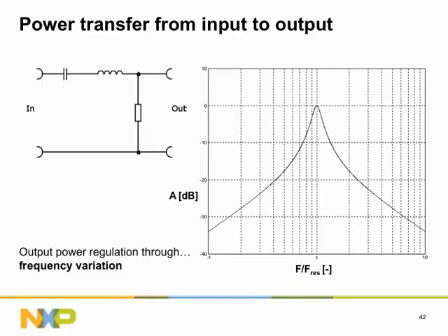In the subsequent course module, more details of resonant converters will be presented. In order to generate exactly the right amount of power on the output that is desired, the output must be monitored, and that information must be presented to the resonant controller via a feedback loop. This control and feedback loop is not essentially different from a loop that is used together with a flyback converter.